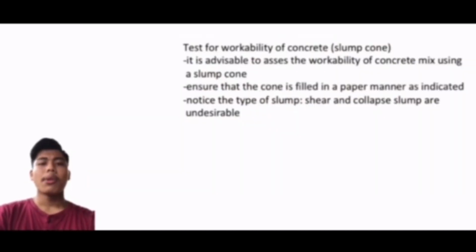The test for workability of concrete is the slump cone. It is advisable to assess the workability of a concrete mix using a slump cone. Ensure that the cone is filled in a proper manner as indicated. Notice the type of slump: shear and collapse slump are undesirable.